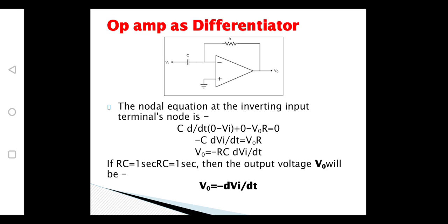We know that the op-amp should be connected in a closed loop gain, whether in the inverting or non-inverting mode. But in order to improve the utility of an op-amp, we need to connect a negative feedback path to it. That is the reason that in all the circuits we feed the output back to the negative input terminal.